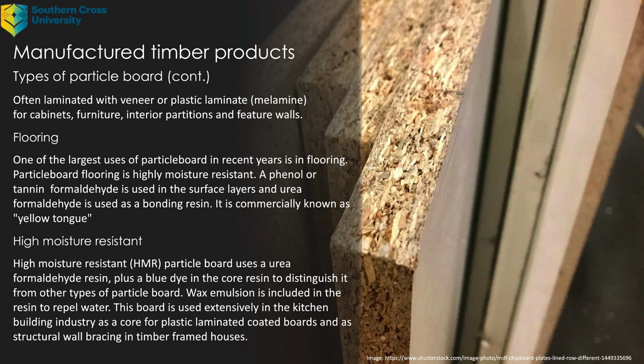It's highly moisture resistant. A phenol or tannin formaldehyde, so a slightly different kind of formaldehyde, is used in the surface layers, and urea formaldehyde is used as a bonding resin through the middle. It's commercially known as yellow tongue.